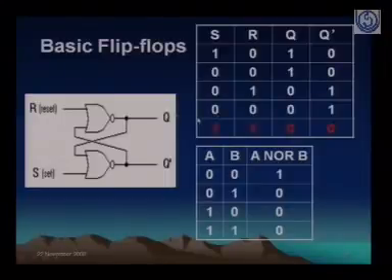Now the flip-flop will remain in the set state even if we move S to 0. Let's try that particular situation. So now S moves to 0. R was already 0, so that is fine. The flip-flop should remain in the set state. Then only will we be assured that this flip-flop is still in the set state, so it is maintaining the state. In other words, it has become a storage element and it is remembering 1 in that particular sense.